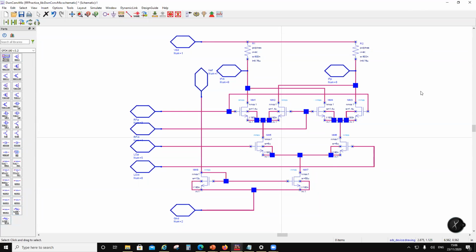So this PDK is not going to be good for that. It is only for proving your concepts to yourself and doing some kind of initial study. But I would recommend that you sign up with the Foundry and get their ADS PDK.